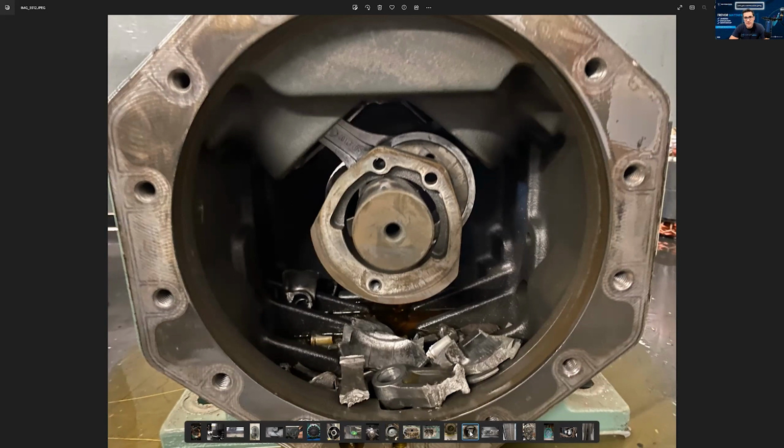So you need to investigate. Is there oil in there? Is there not? Is there overheating? Is there not? This is why inspection is so important, even on scroll compressors, or hermetic. Same thing with a hermetic. If you have two or three compressors fail, you need to check it, because what's going to happen to the next one, and what causes it?